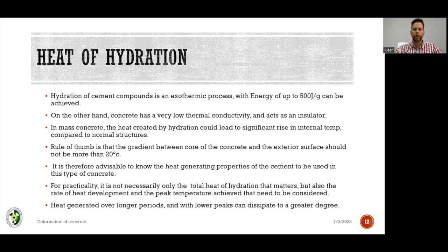What happens then to the concrete truck? As soon as it's batched, it removes itself from under the plant and goes and parks at the inspection platform, where the concrete is monitored visually for slump, whether the mix is responding according to the mix criteria and the mix design that was prescribed. So there's a batching sequence that's followed. Your coarse aggregate, your fine aggregates, your cement and your cementitious extenders, as well as your admixtures, all get added or pre-batched, then loaded into your truck and mixed.